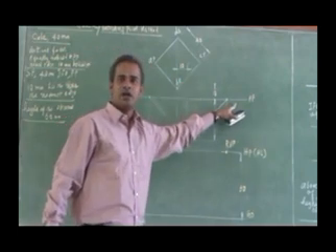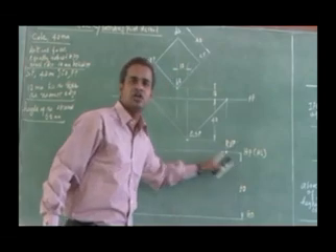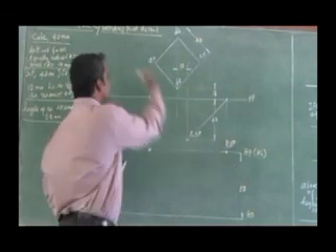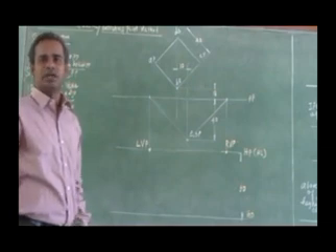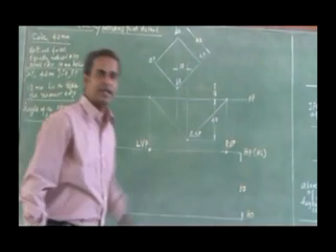So I will obtain it on the picture plane by dropping that to the horizontal line. I will obtain the right vanishing point. Similarly, I have got the left vanishing point. Now to get the perspective, you don't have the front view. What do I have to do?